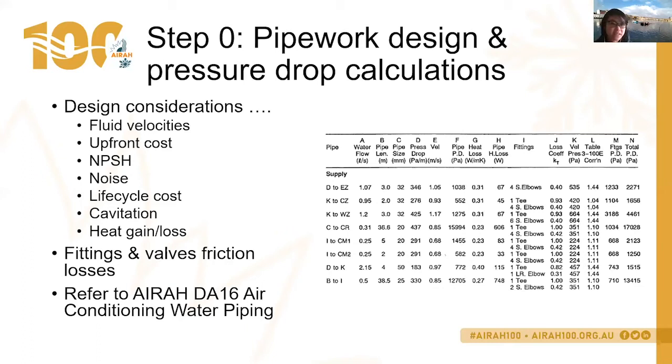You need to consider how you can avoid cavitation, and you may also need to consider what the heat gain or loss is, because it affects your coil delta T. Obviously, you'll also be looking at fittings and valves friction losses, which are not considered. There are no compliance requirements in the NCC at this stage.